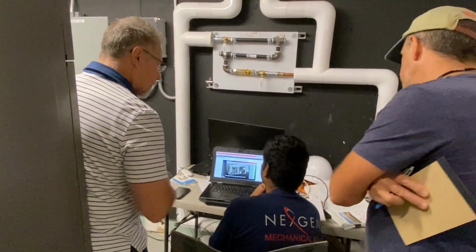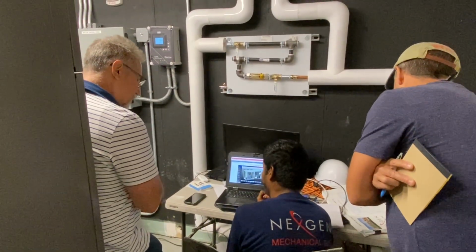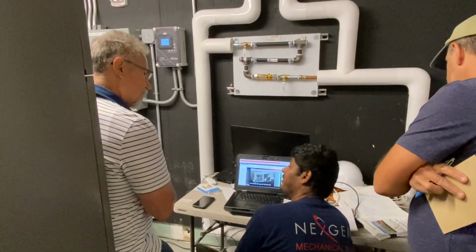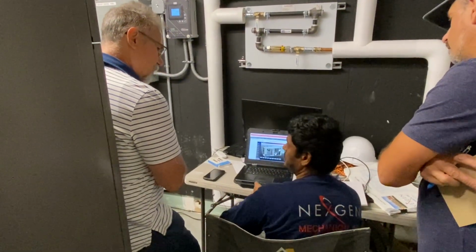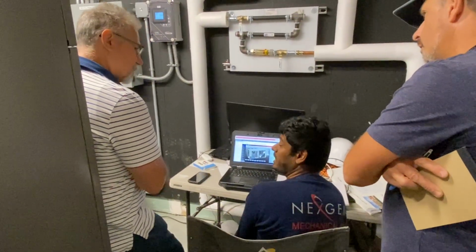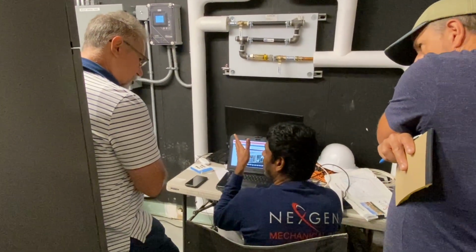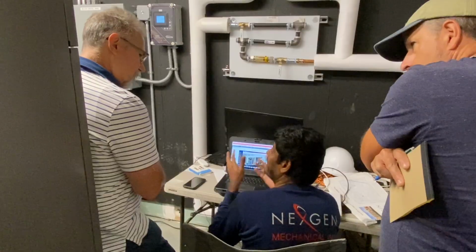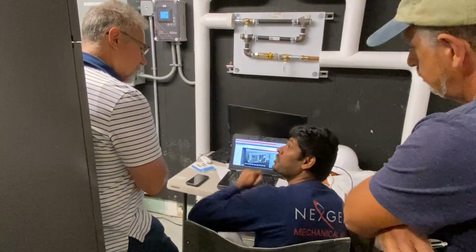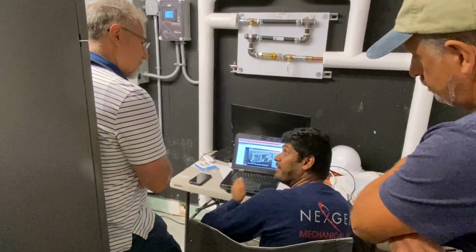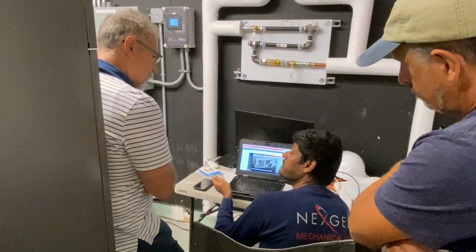So that's the energy wheel operation, and we also do some freeze protection on the wheel. For example, if the outside air temperature is, let's say, adjustable, less than 30 degrees Fahrenheit, and the pressure across my wheel goes more than 1 inch of water column, then I assume it's frost. Then I spin my wheel very slowly to defrost it. So there is a defrost operation going on in the sequence.